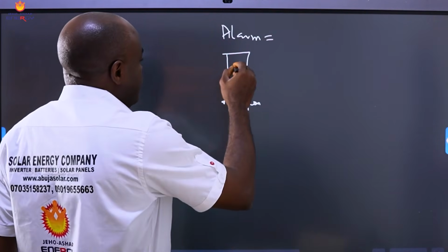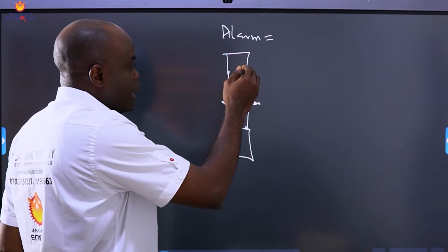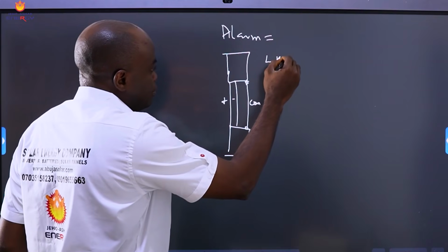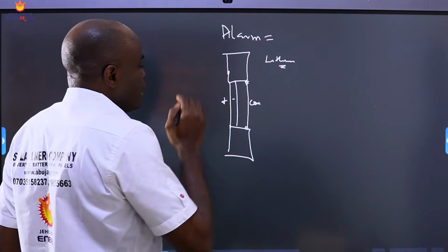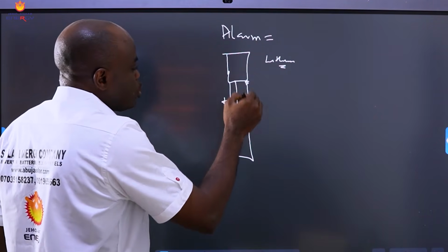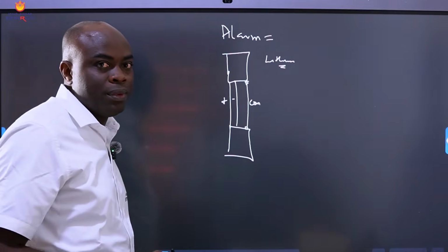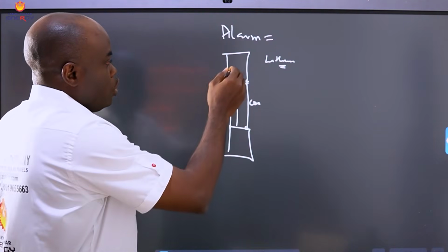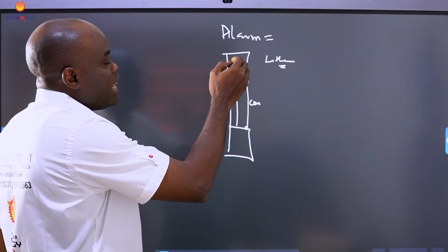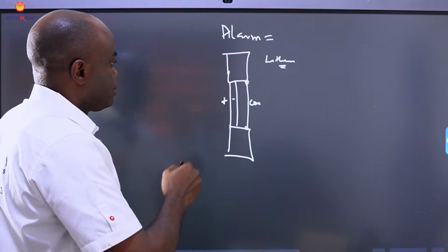First, if you have selected lithium, and there is no communication cable between the battery and the inverter, the inverter will give you an alarm. And likewise the battery will give you an alarm, because you didn't select any communication between them.